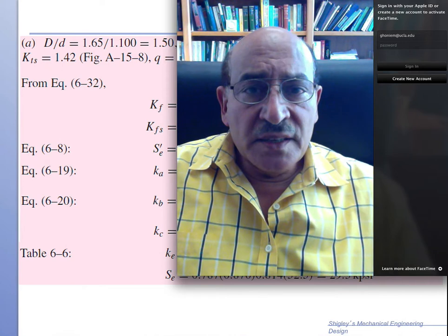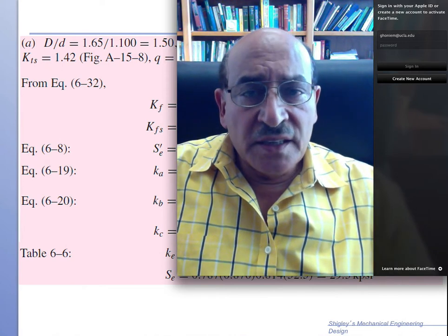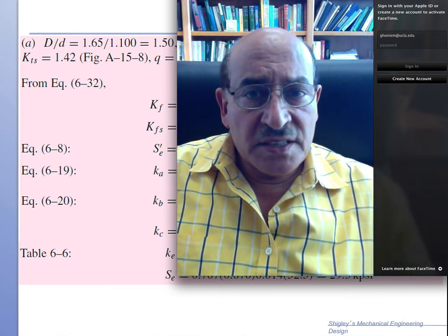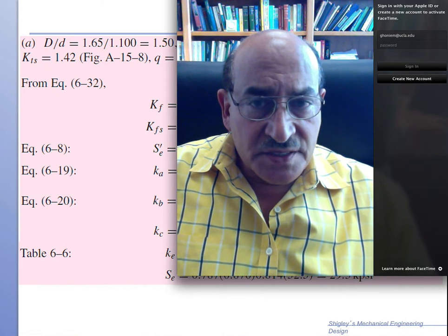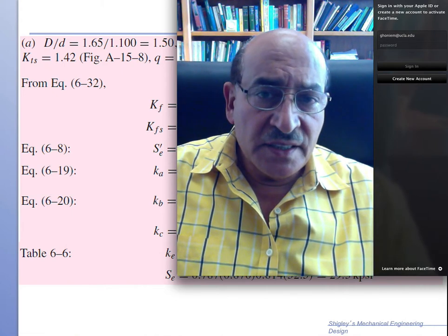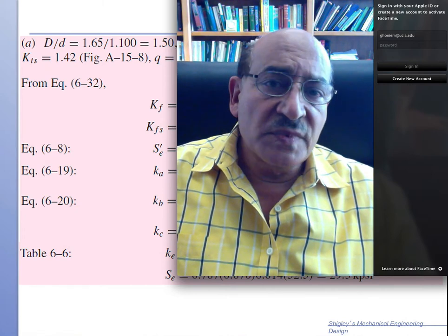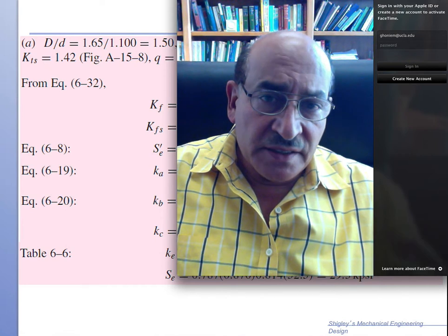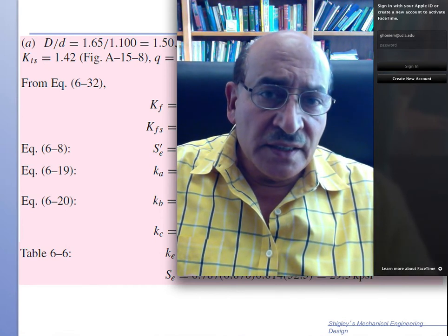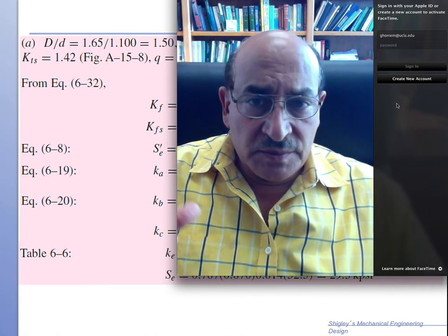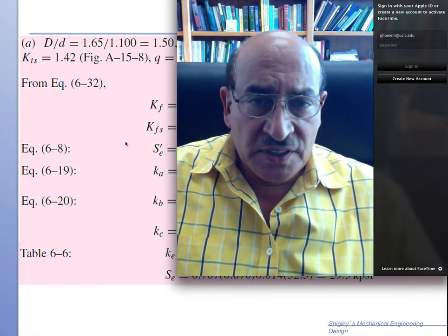Next, we have to do the loading, and we get the bending stress, and the torsion can induce shear. Not only that, but we have to find the stress concentration factors. Those we usually obtain from figures under static conditions. And then we have to use the notch sensitivity factor for fatigue to make corrections to these factors and derive the corresponding stress concentration factors in fatigue.